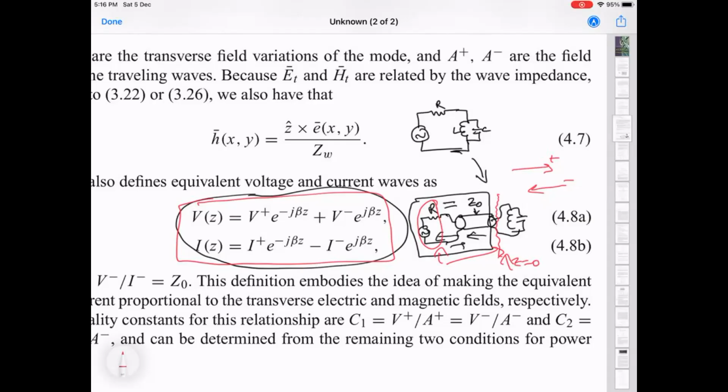And that then gives you a circuit relationship to say that there is a current and voltage at this point. I can now equate that to the currents and voltages which I expect to be flowing in this circuit in terms of its dynamic variables. For example, if the charge is Q and the flux in this inductor is phi, then the total current at that point is basically phi over L plus Q dot, right? We had written it down. So these are the two conjugate variables you can use to define the dynamics of this. And of course, one can represent one in terms of the other and get rid of one of the two variables completely, which is fine.